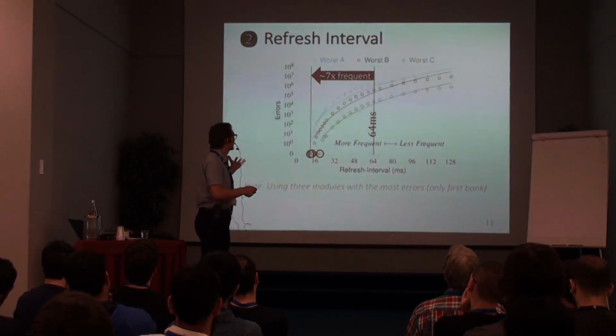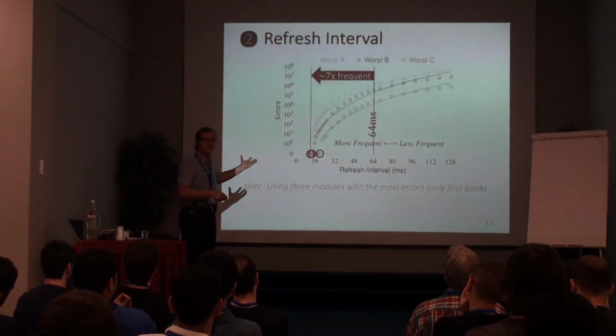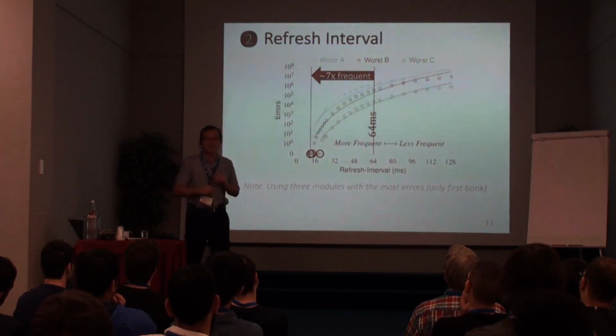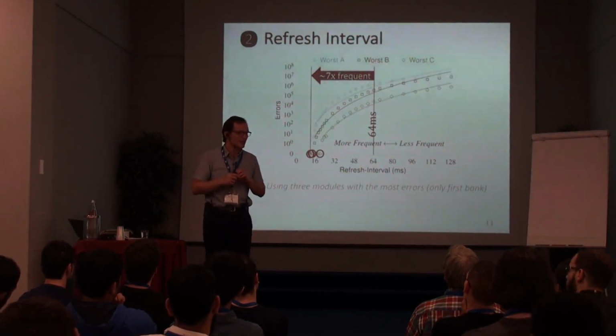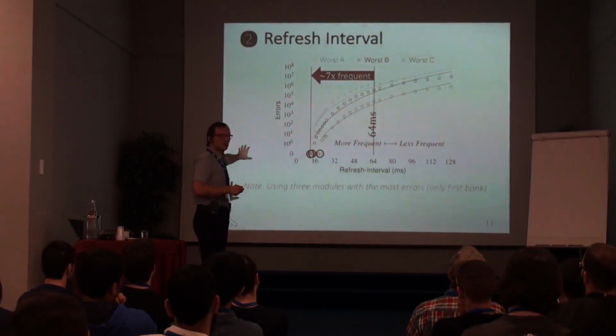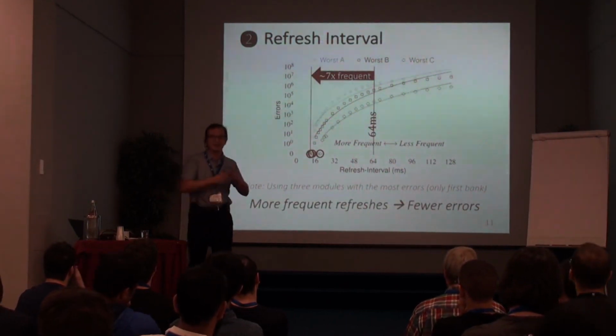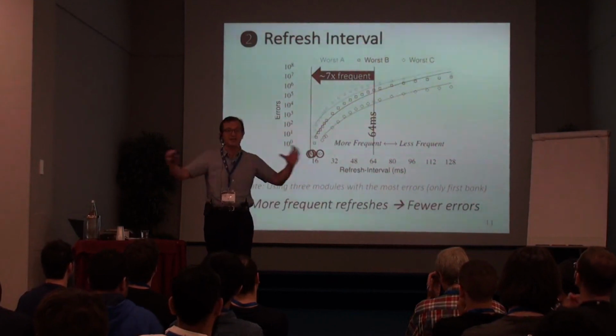This sort of errors you can mitigate by increasing the refresh rate. You get rid of errors, but it comes at a cost, as you can see, right? Energy cost, performance cost, quality of service cost. So this is not a good solution, as we discussed yesterday, even though it solves the problem, because it's really increasing the refresh rate across the entire DRAM.